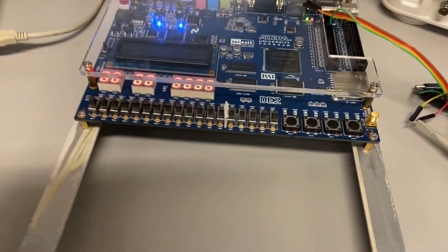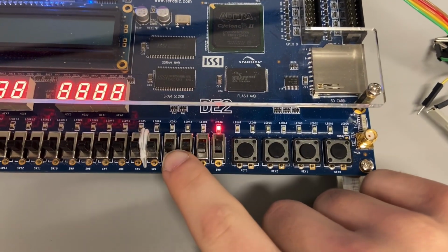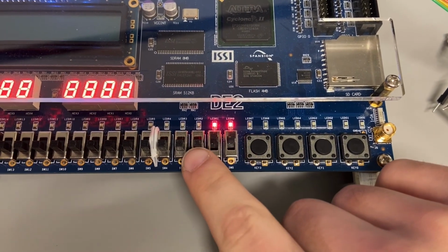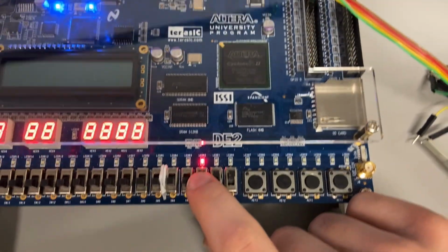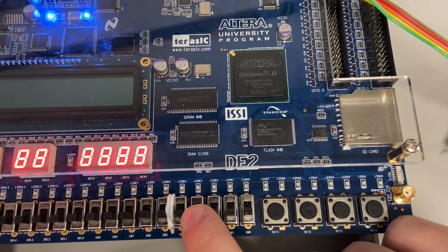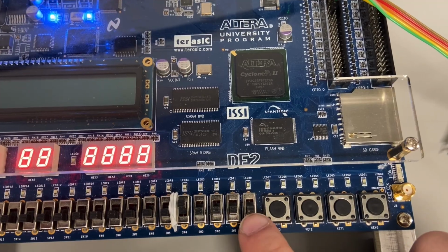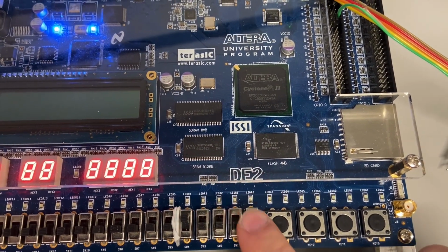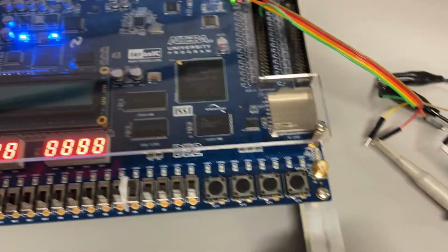And if we go over here to the hardware test on the board, we can see that we can add 1, we can have 2, or sorry, 3, and then add 1 more, which then triggers the overflow indicator right here. And then we can, let's see, I believe this was mode. So if we have 0 and we subtract 1 from it, then we have 1 with an overflow. If we have 1 and we subtract 1, we get nothing. So it's working as desired.